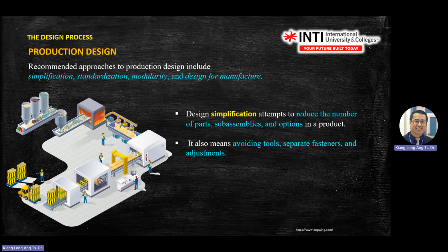For example, if you buy a gaming PC laptop that you self-assemble, nowadays if you want to change the processor, the IC chip, it's very easy. You just need to press, and there's a spring mechanism to push the object out. Sometimes also, if you're installing computer RAM, there is a slot you can slot it into. If you install it in the wrong direction, you cannot slot it in. Most designs nowadays use Poka-yoke design. Poka-yoke means error-avoiding design.